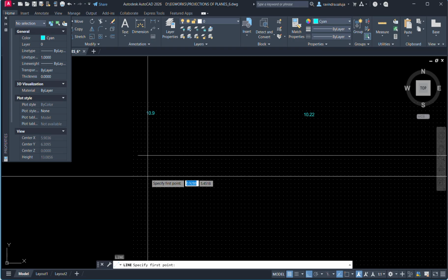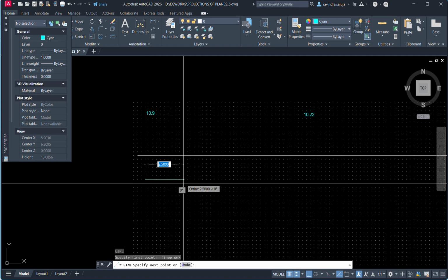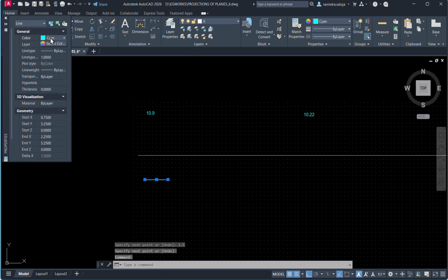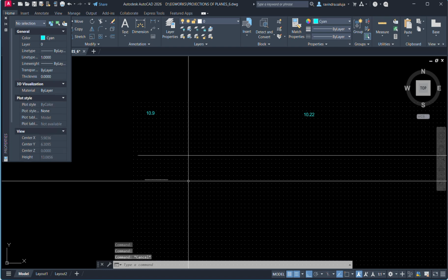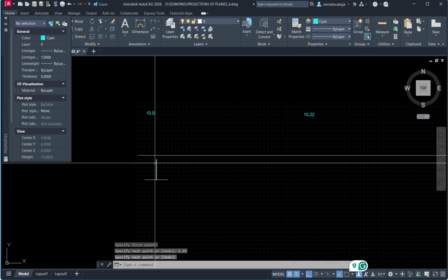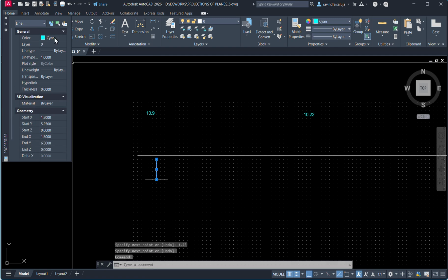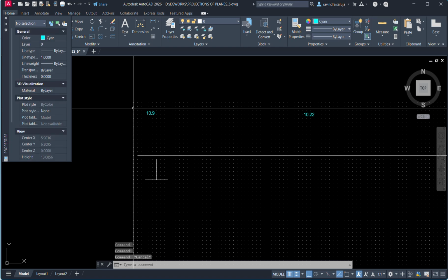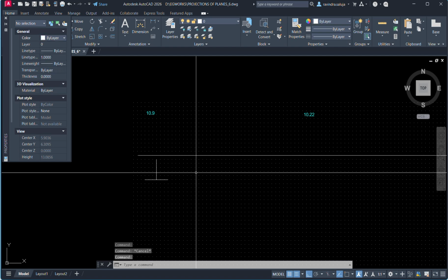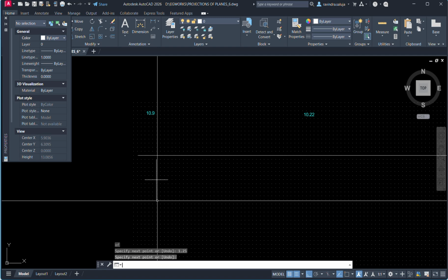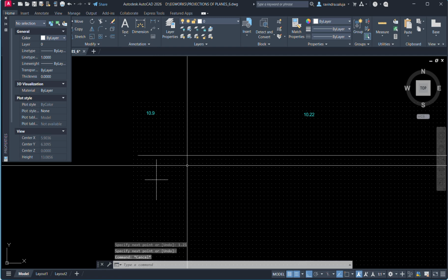AC. So 150 mm means 1.5 AutoCAD units. So we change the color, sorry, the layer. Now 250 mm means from here how much? 1.25, okay? And on the below side also 1.25. Now we need to join these to create a rhombus.